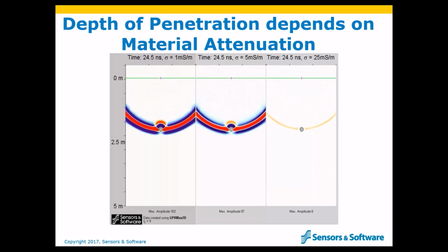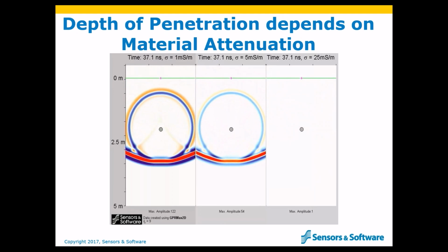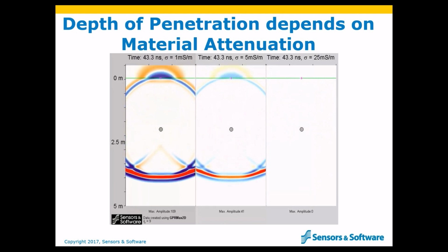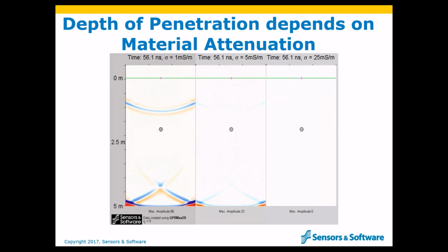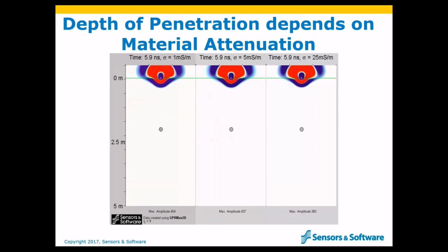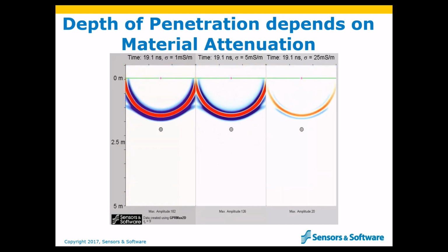They drop behind that quite quickly, so the penetration depth may only be a few feet. A coarser grained soil like silt, depicted in the middle of this animation, has lower electrical conductivity. The signal absorption is not as rapid, so the GPR signal travels deeper before it drops into the noise.